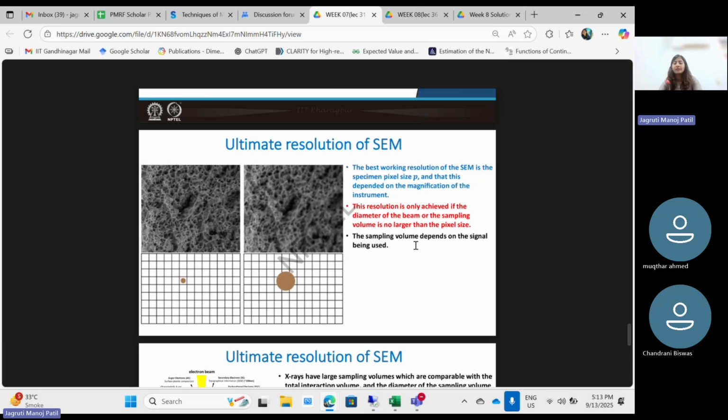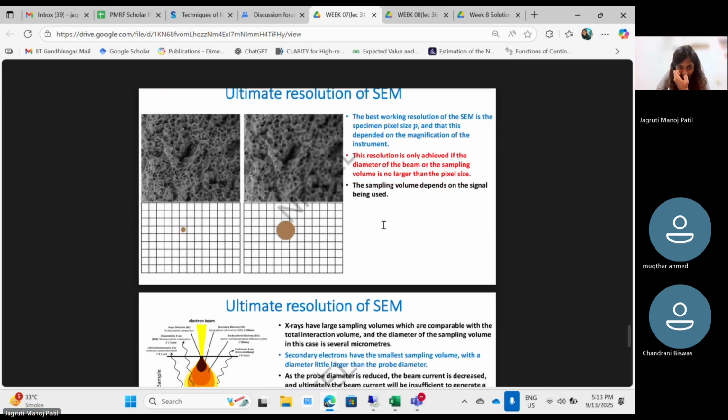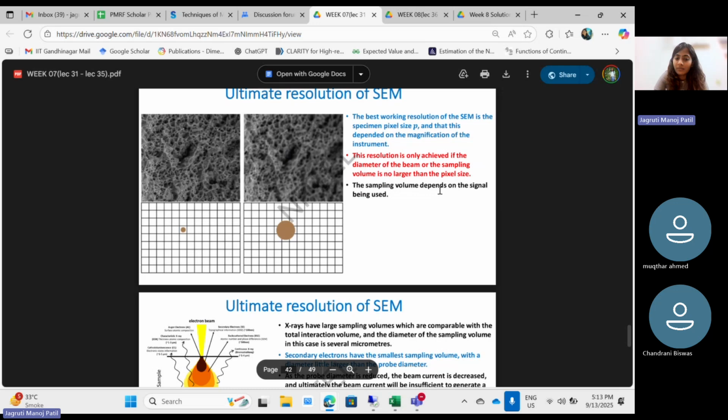That is defined by one very popular theorem, the Nyquist-Shannon theorem. What the Nyquist-Shannon theorem says is that the minimum sampling frequency should be twice the maximum frequency. And sometimes, conventionally, we always use 4 times the maximum frequency. It can always be higher because oversampling is not an issue, but undersampling is an issue because it will cause aliasing. Eventually, aliasing will lead to loss of information, right? Because of that, you sometimes lose your information and you get blurry images. And hence your resolution will also be affected because of it, right?